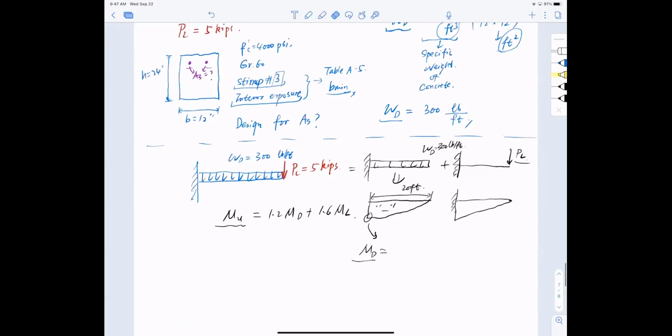Yes. So what will be the moment here, MD, at the end of it? That equals the total force applied on the cantilever, right? What will be the total force applied on the cantilever from the dead load only? Let's do a separation. Don't worry about the live load, just do the dead load. What is that? Distributed load omega D multiplied by what? Multiplied by the total length, right? That is the total force by the dead load. Now I got the force, I need to know the distance. And Fahad, in case you forgot, the distance is half L, right? So that is the moment applied to it.